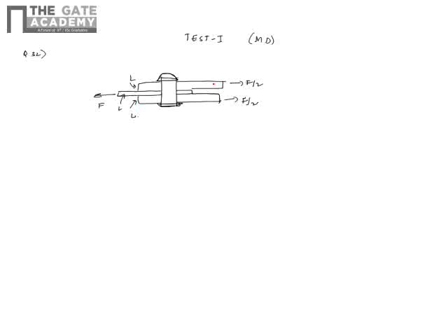Okay, so now when you apply this sort of geometry, when you're pulling this towards left and these two towards right, the shear happens here. So if I take only the middle plate, and the rivet being this, when applying total F here, this part and this part, so it's something like this. When I apply F here, the shear forces are created here and here. So this F is supported by F by 2 and F by 2.